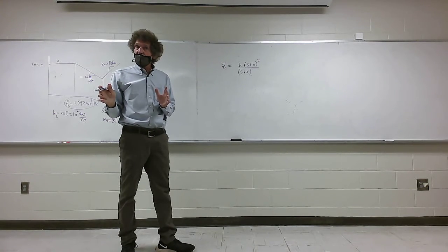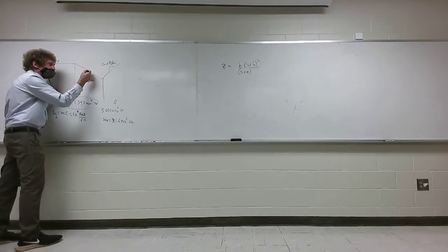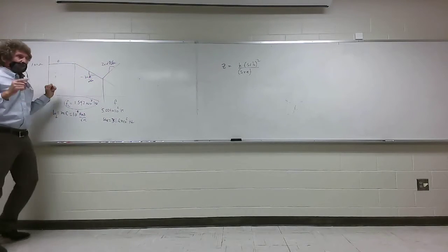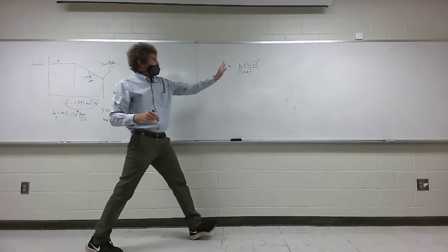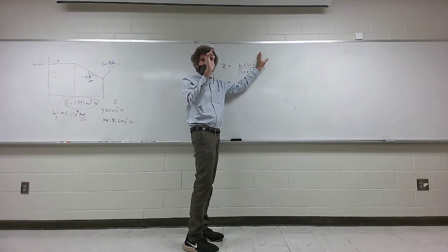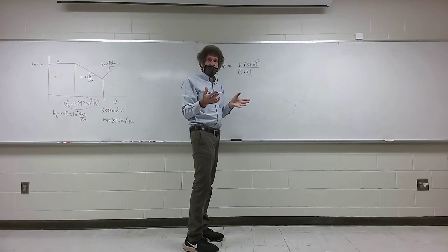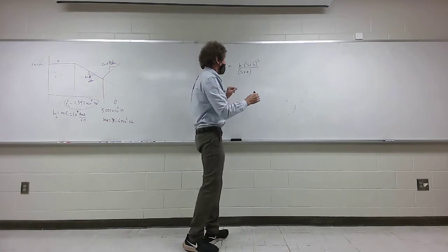How do you know that's squared? All right, here's how I did it. See how this is going down at 20 dB per decade? If it was a single pole, it would just be flat. So that would be just S plus B. But because it's going up at an additional 20 dB, I square it. Y'all follow me on why that's true, right? If it was going up at 60 dB per decade, what would I do? To the third. It would be S plus B to the third.